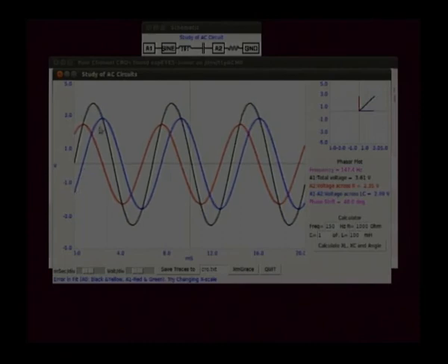See the blue trace. See here it is at 0 crossing, it is at 0, but already the current is at the peak. That means you can see the voltage across the capacitor, the current is ahead. The phase relation between the total voltage and the current is shown here by the phasor diagram. And also you see here the observed values are plotted: the frequency is 147.4 hertz, total voltage is 3.61,